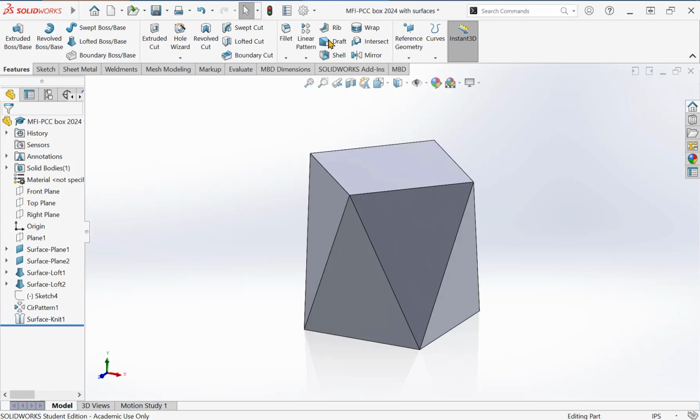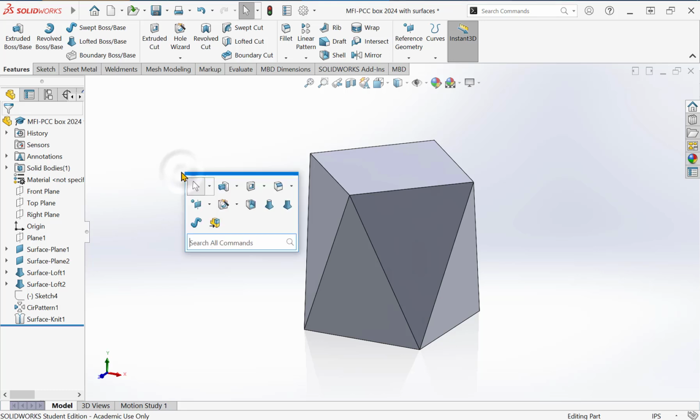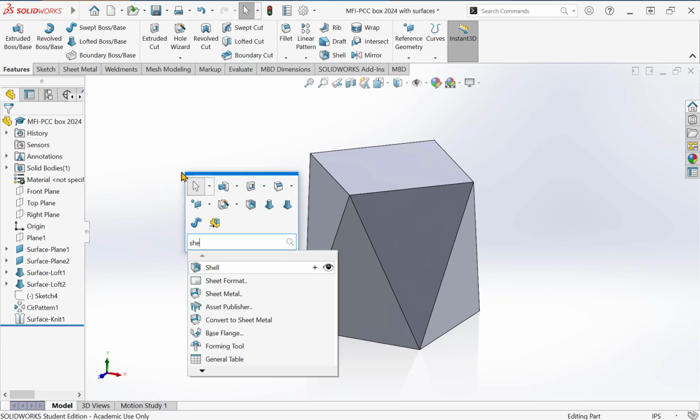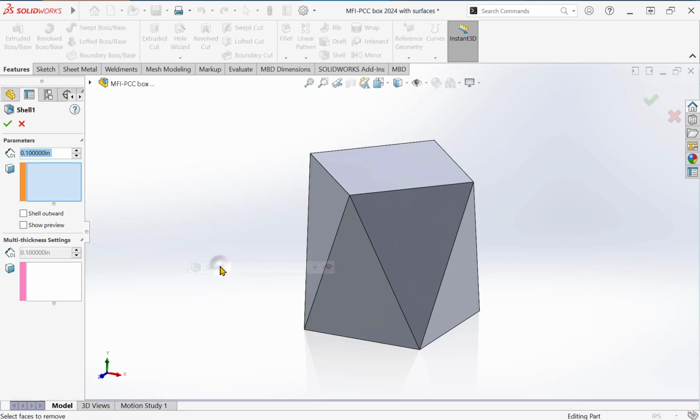So in SolidWorks, the feature that hollows something out is called shell. And the shell feature works directly on the body. There's no need for a sketch. The first box, the thickness, is whatever material you're going to use, and your boxes will be made out of 0.040 or 40 thousandths thick aluminum, or 1 millimeter. So we'll type in 0.040.